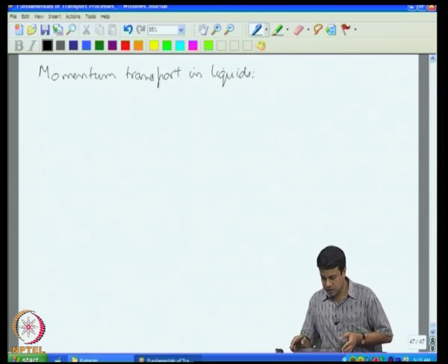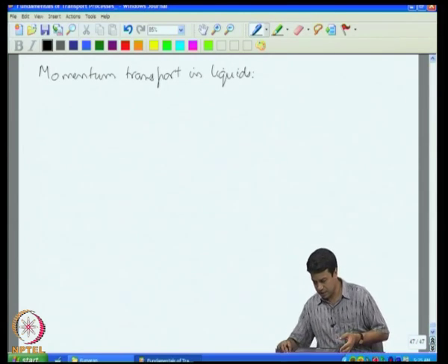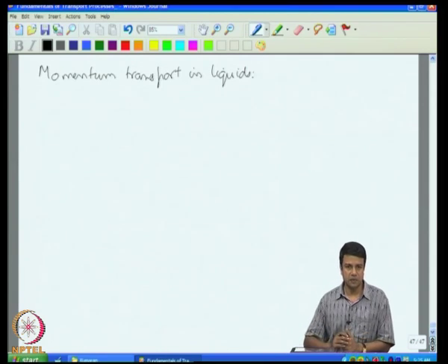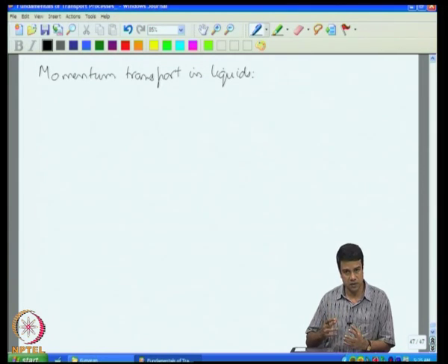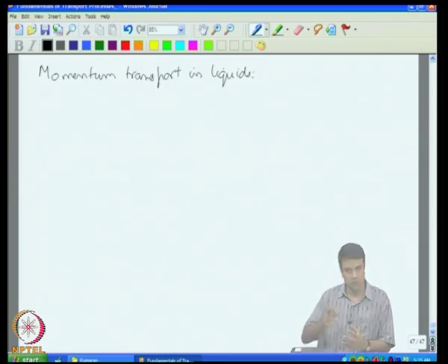When we discussed mass transport, I had said that naively you would expect the mass diffusivity for liquids to be about 10 to 100 times smaller than that in gases, simply because the mean free path is smaller and the fluctuating velocity is approximately the same. It turns out not to be so. For the physical motion of molecules, you require all molecules around it to also move, because the transport of solute molecules requires that particular molecule to diffuse through the fluid.